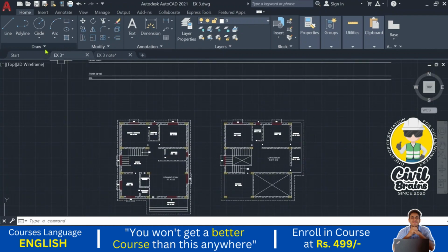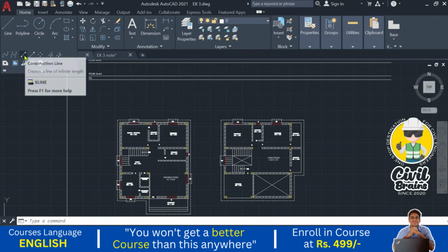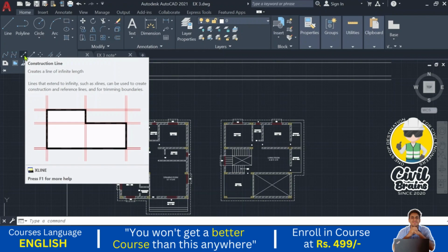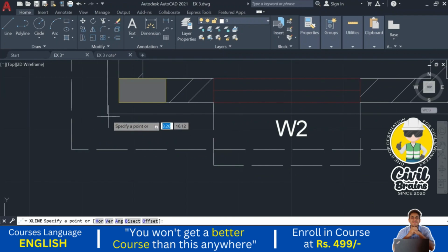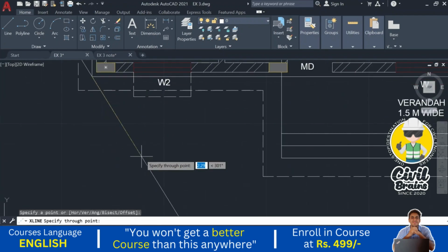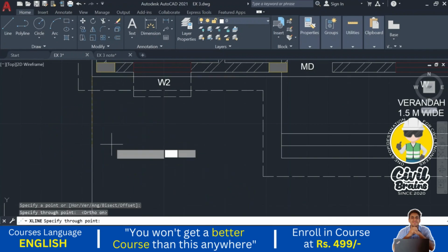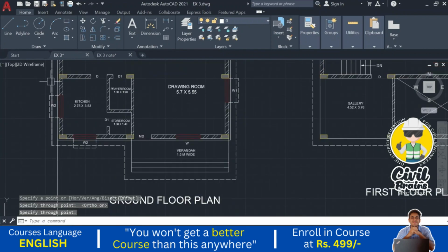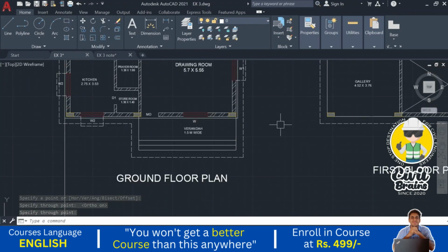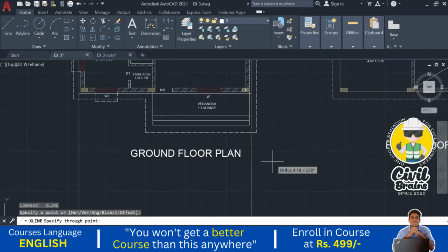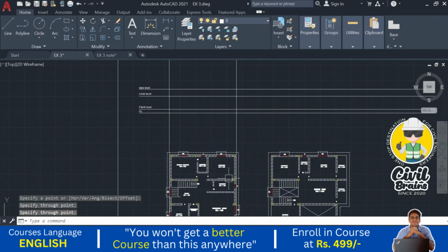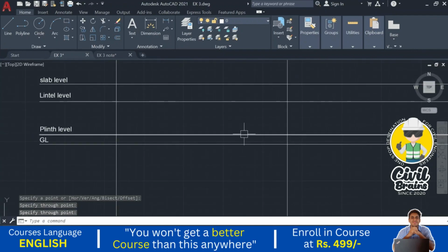So now I draw the plinth first. I go to the construction line. Here you can see this one. Using this construction line, I project the things. Go to the construction line. You add it at the corner of this one. Okay, so it is not straight. So for that I turn on the ortho. Press enter. Again, I want that construction line. So to repeat that command, I press the space so that the same command will come. I press enter. Okay, so this is our plinth boundary.